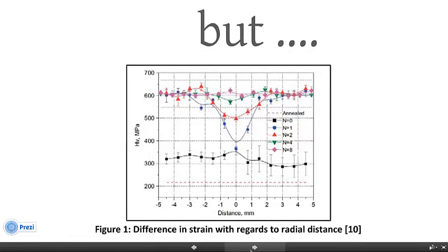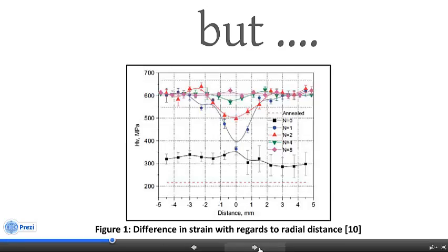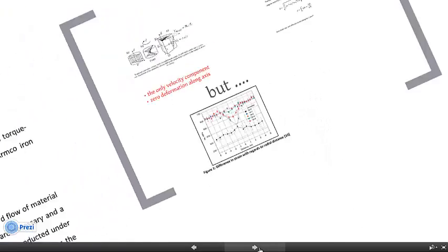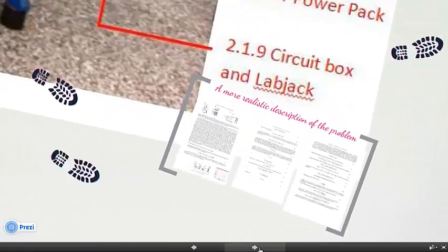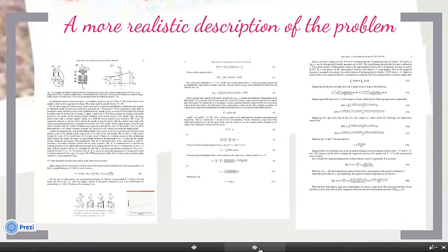When we look at the experimental observation, it doesn't comply with the predictions from this mathematical model. As we repeat the process, the material work hardening and grain refinement tend to become rather uniform, which is by no means the linear work hardening predicted by the existing model. So let's have a totally different view angle toward the problem, something more realistic.